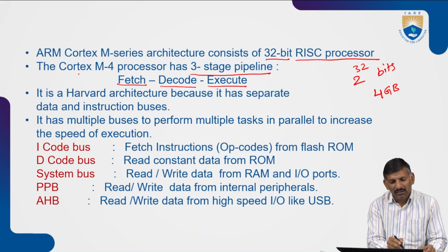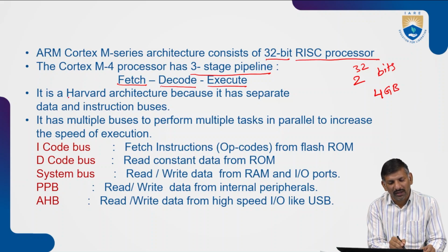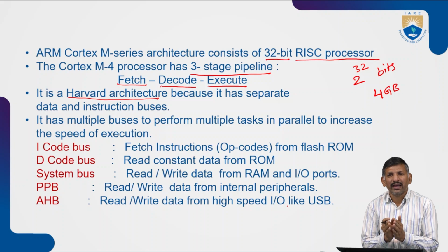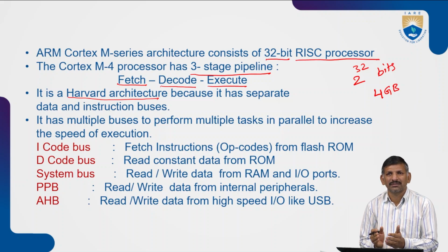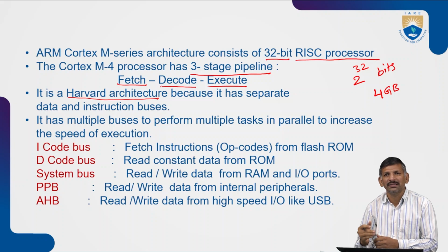Next, the Cortex-M4 series architecture supports the Harvard processor architecture, which means the processor has separate buses for fetching instructions as well as data.